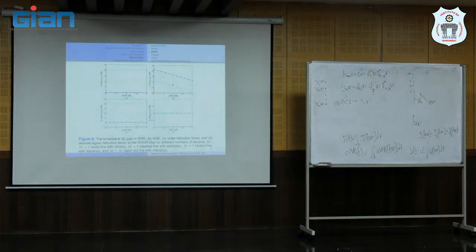If we use the maximum SNR filter, what will happen to the noise reduction compared to MVDR and Wiener? So the maximum SNR, you know, it will suppress more noise, more than the Wiener. So the noise reduction will be even higher, but the distortion will be even higher than the Wiener. Okay, so we know the relations between different filters and the objectives, and we understand what they do.